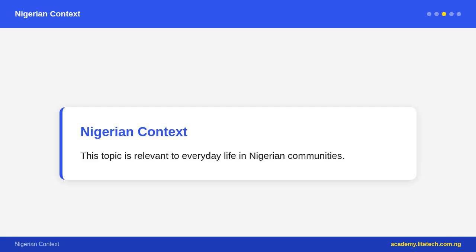Key property of inductors: electromagnetic induction. An inductor opposes changes in current flowing through it. When current increases, the inductor produces a voltage that opposes the increase. It stores energy in the magnetic field. When current decreases, the inductor releases the stored energy back into the circuit, trying to maintain the current.